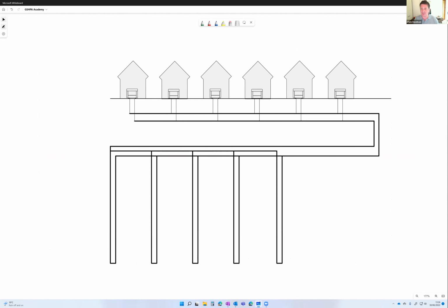If we've got a good number of buildings connected together, then we can take a diversity factor on the heating profiles for those buildings. So you can assume that not all these heat pumps are going to be running at the same time. One's off and the other 5 are on in this instance. That might allow you to get away with fewer or less deep boreholes, so it's going to give you a better borehole installation cost.